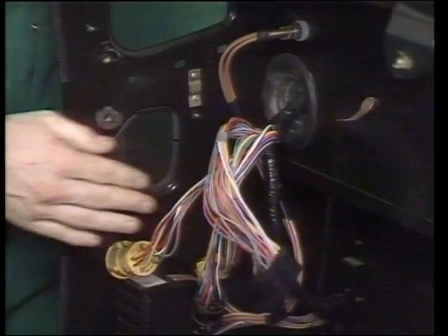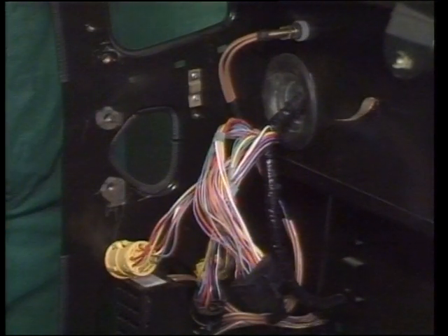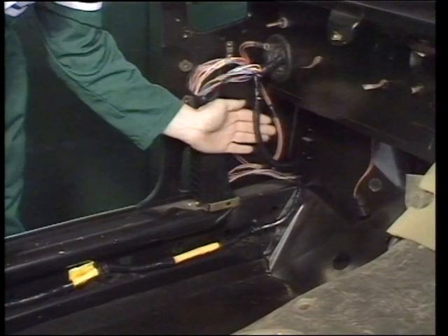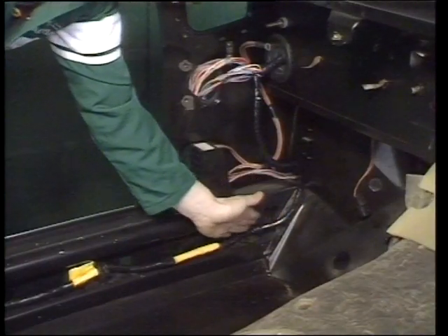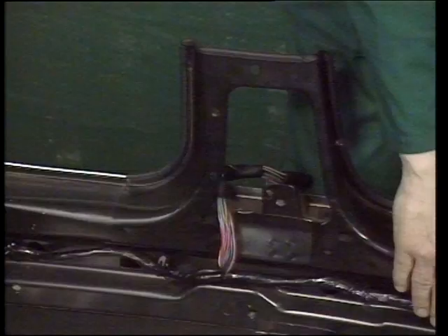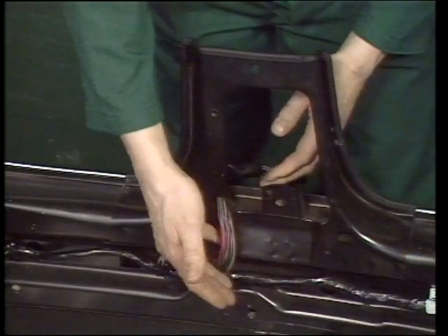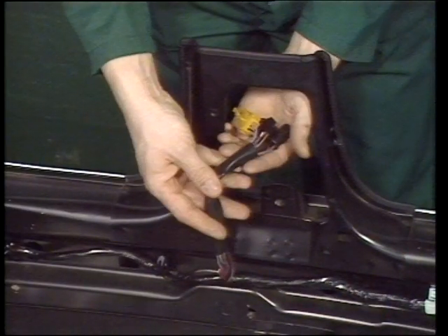Here there's a breakout from the side harness carrying the leads for the interior lamps and the sunroof. From here, the side harness is then run down the A-post inside the car, where it's recessed into the sill and run up to the BC post. At this point, there's another breakout of wiring which will be fed to the rear door speaker, the left-hand side door locks and the window controls.